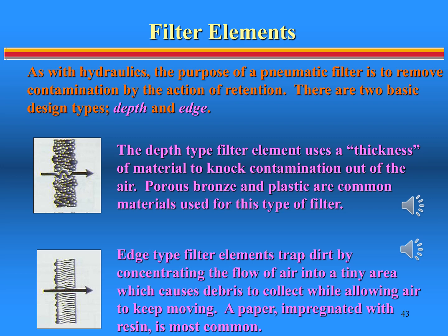Fine and microfilters remove particles smaller than 1 micron down to 0.01 microns. The air flows through the filter cartridge from the inside to the outside. Solid particles get stuck in the filter cartridge, clogging it up.